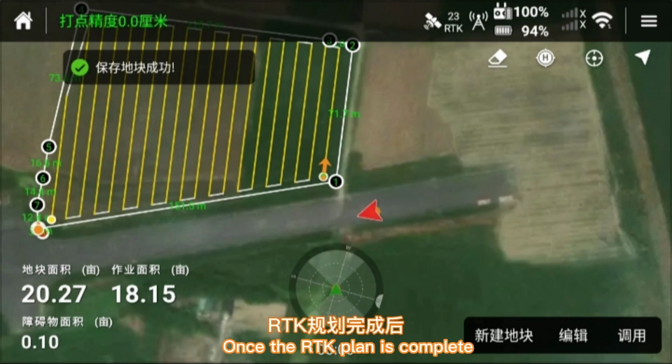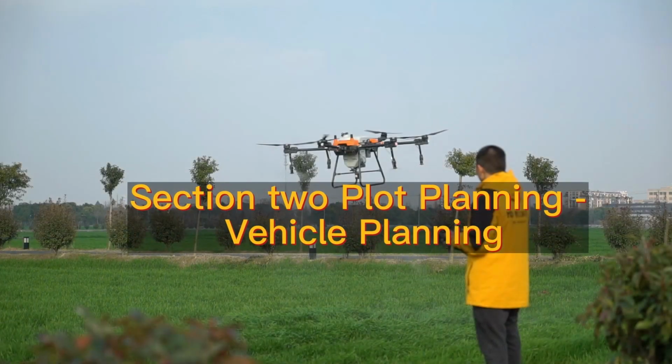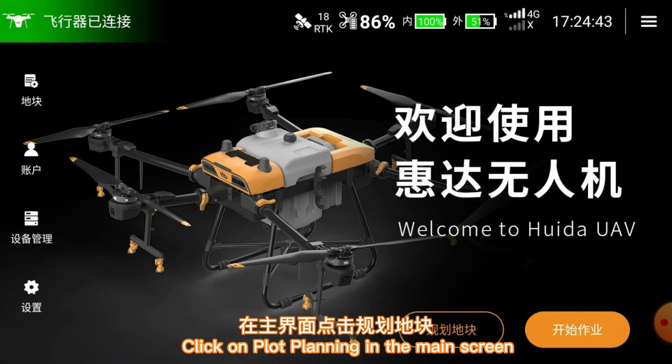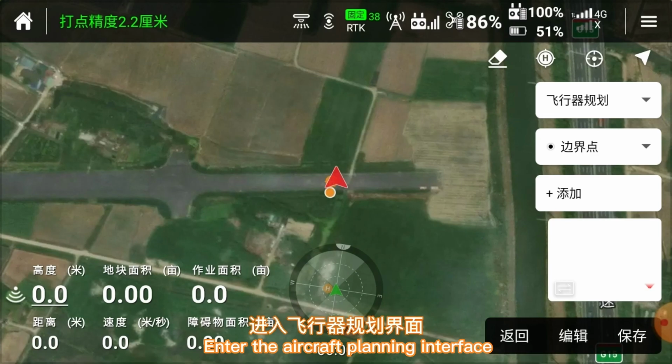Once the RTK plan is complete, you can edit the new plot by clicking on the bottom right-hand corner. Open the remote control to enter the main interface. Click on Plot Planning in the main screen. Click on Aircraft Planning. Enter the Aircraft Planning interface.